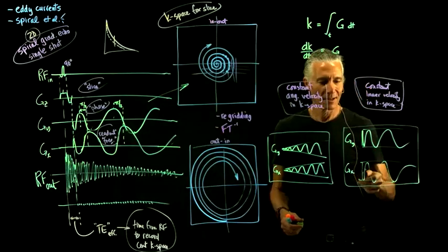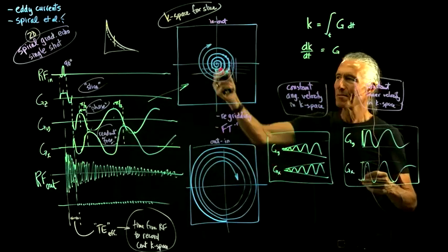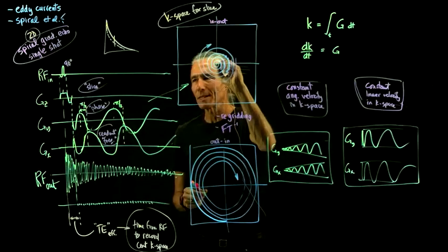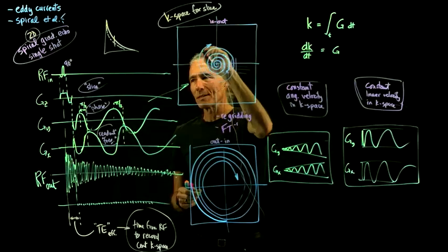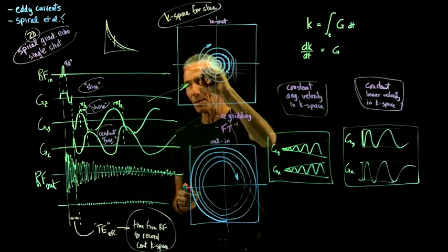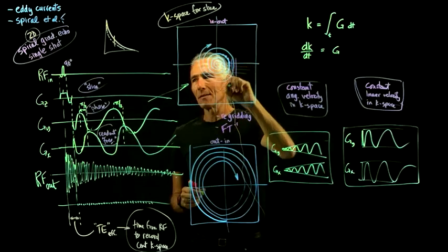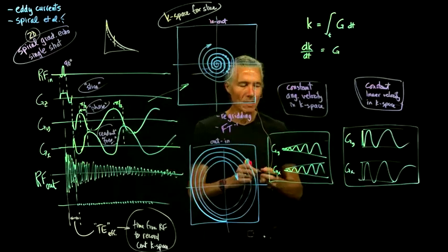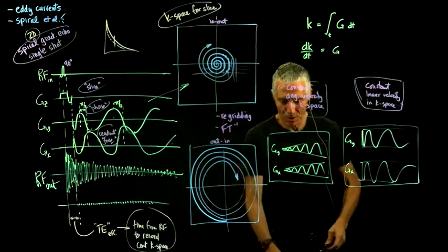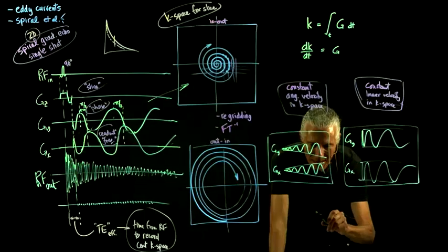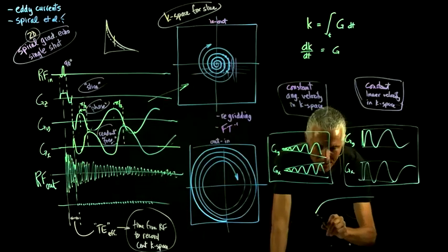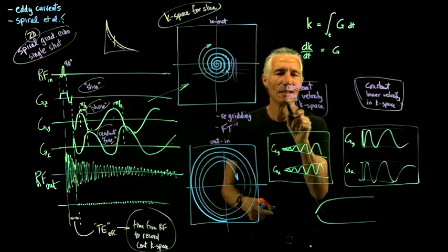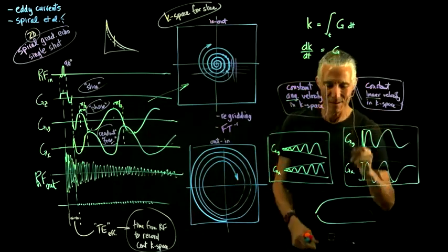The gradients are getting very vertical right at the center when you've got to go around really quickly. And then as you're going the same speed through k-space along the spiral, your gradients can be less packed. And so usually in practice what people use is a combination of those two. Start off at constant angular velocity and then end up at constant linear velocity.